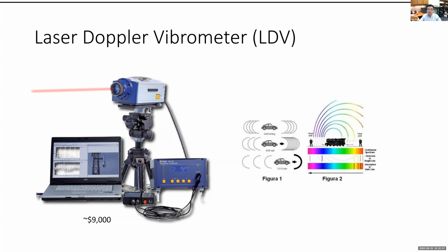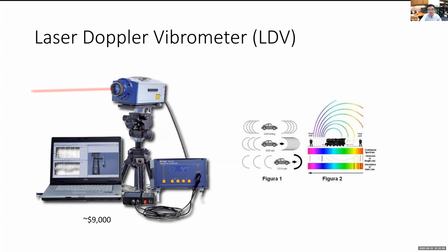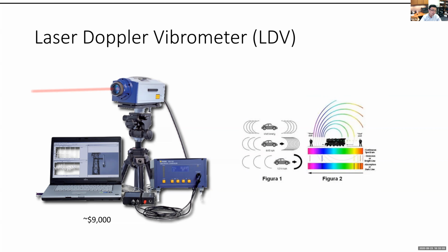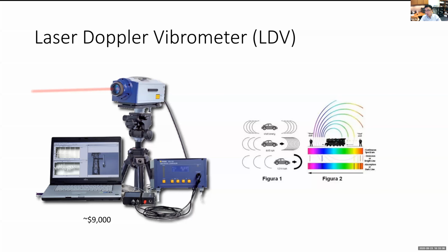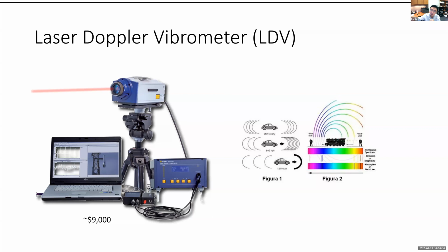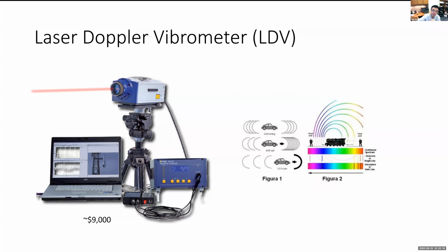Okay, so now let's come back to civil engineering. The laser Doppler vibrometer is often used to check structures, for example, a bridge or a building. And the benefit of using this one is what? It is contactless. This is a contact-free method. So if there's no way for me to go, let's say after an earthquake or something inaccessible, I can basically put this laser Doppler vibrometer and shoot at the object. I can still tell the vibration.